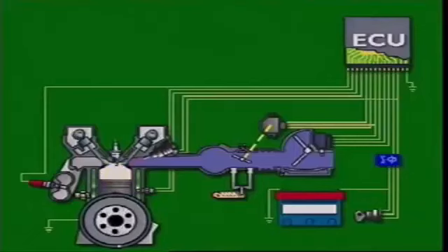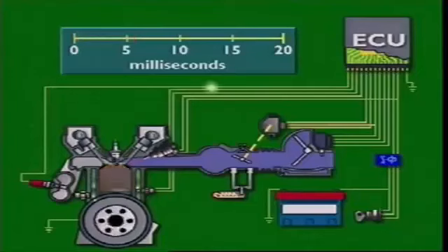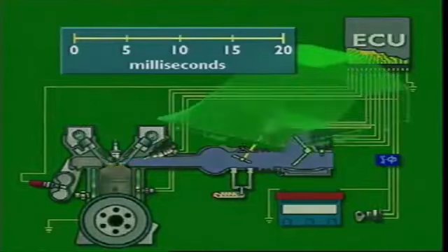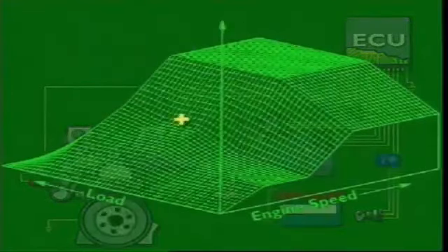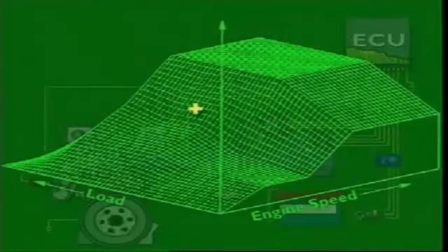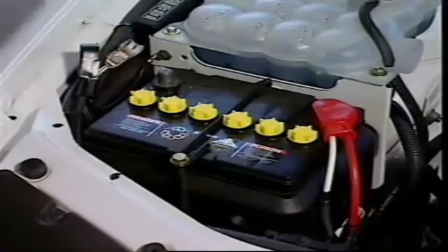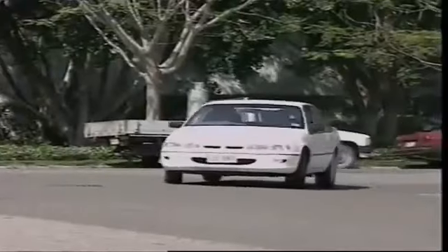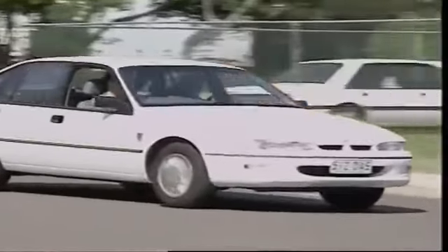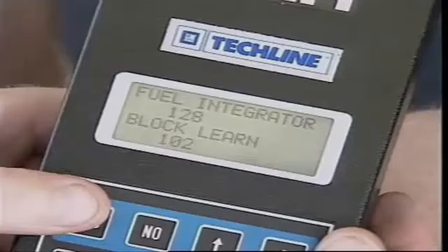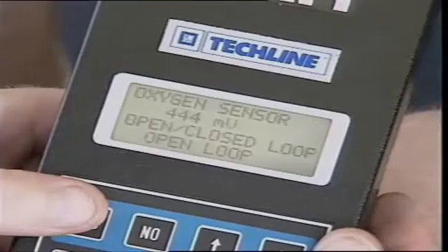However, if fuel pressure is less than when the vehicle was new, feedback from the oxygen sensor can cause the lambda control to increase injection time. The control unit learns the new time and stores it in its memory for future use in that condition. If the battery is disconnected or memory is lost, the settings revert to the manufacturer's program specifications. And the vehicle then has to be driven in a range of conditions to let the control unit, in effect, relearn the engine's fuel settings.